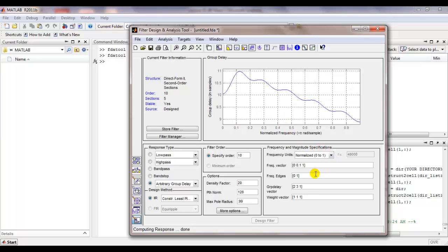Now you want it at pi to reach back to 1, so you want a -2. You want a downward trend of -2 group delay. Okay? And so it has tried to go, it's not again a straight line, it has tried to go from 11 to 9. It can't exactly hit 9 because again it's a numerical method. It can't exactly give you what you desire.